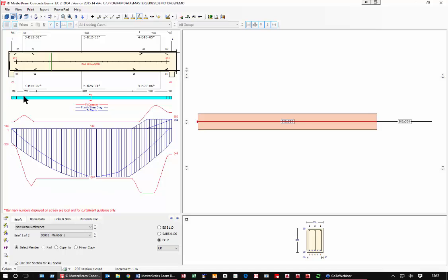So we're now coming in nice and neat with 4/16s lapping in. And on the top we've got 3s and 4s. I don't like that. I prefer to use the 5 bars in the middle, and then we just lap it with 4s in the ends, because we don't need that extra bar around there. And we can see our links.